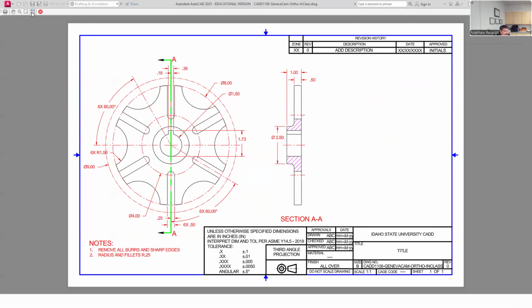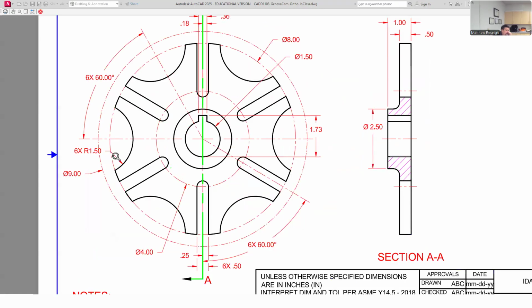I might need to see if I can get that to pop. You can see how heavy it is. I think I'm going to adjust its scale a little bit and get a little more breakup between the short line and dashes, but it's going to plot that heavy. And it's debatable whether I should delete the center line out from underneath it. Technically, it's a center mark that I made, so when I delete that, I'm going to lose a lot of my reference points for my dimensions. So I'm not going to delete mine. It's going to be this really fine line that shows up underneath it, and I think that's going to look okay.